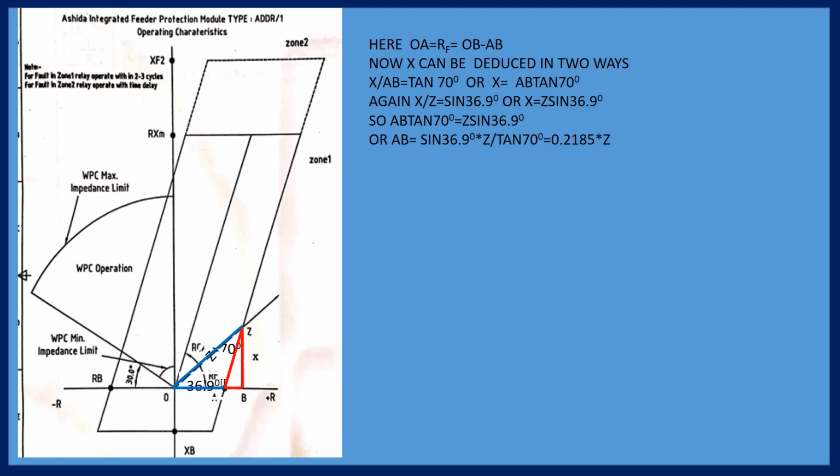Next importance in the substation is the polarity of the current transformer. Power transformer, it is marked, but you need testing. I'll show you that. I have already shown you the polarity test. The transformer you can also test with DC, but an AC test is also there. Later I will show you the AC test.